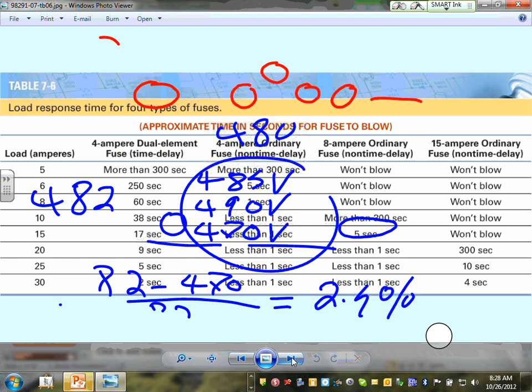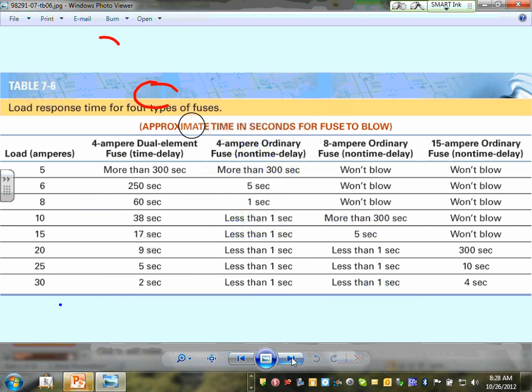Does the panel self-balance the system? Yes. If you have a three-phase panel, it forces you to use phase A, phase B, phase C, A, B, C, A, B, C, as you pull circuits, all the way. So by default, you are balancing them, unless you start at A, skip two circuit breakers, and go again. Who would circuit this way?